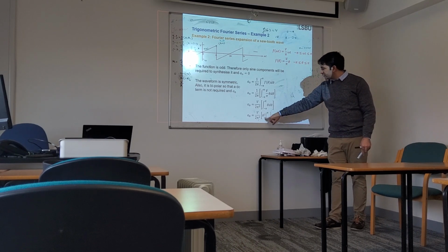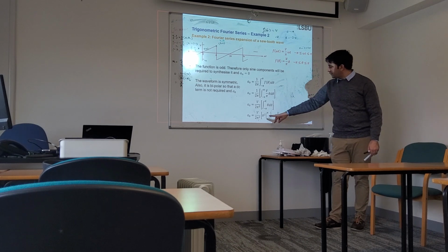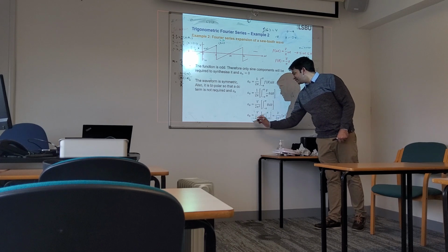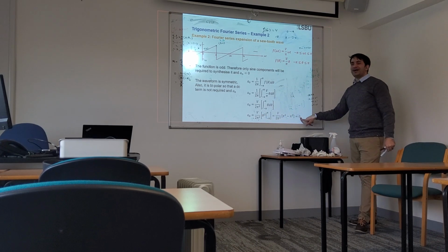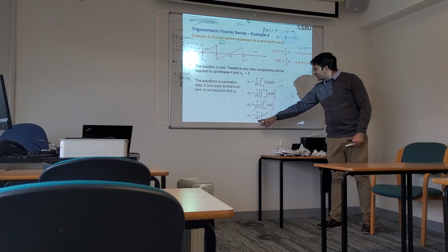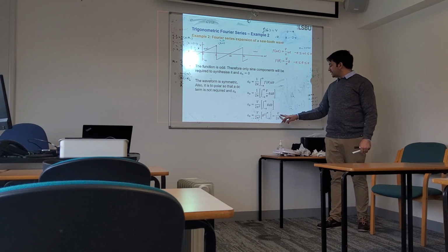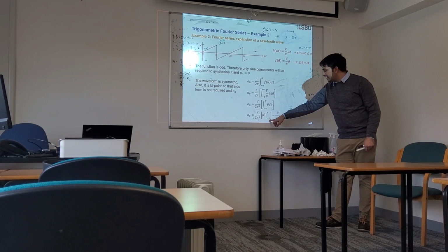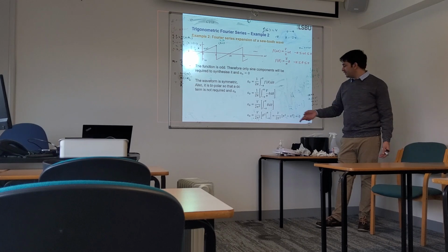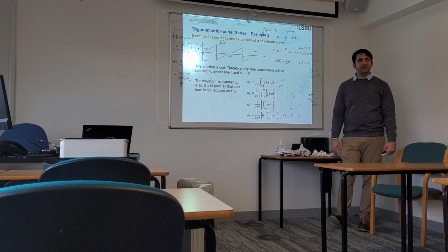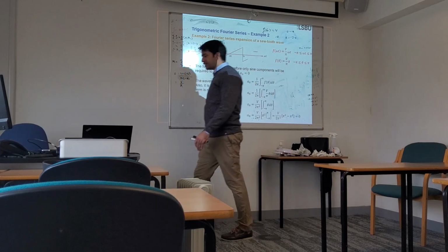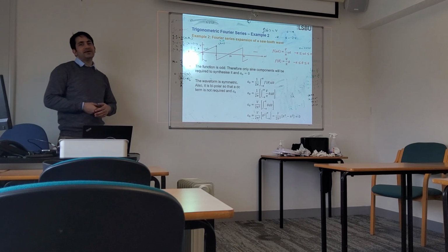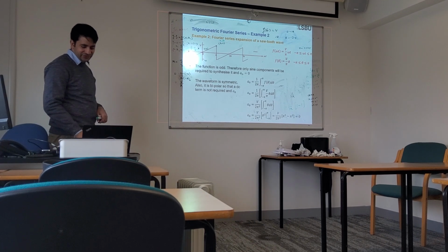So it would be theta squared divided by 2. I don't know where I put 2, but yeah, 2 should come outside. So there is another 2 here. Since I knew the answer is 0, okay. So finally you have theta squared. You put upper limit minus lower limit. So pi squared, then in the lower limit is minus pi, so the square will make it positive. So this will come out as 0. So it means that for an odd signal, the value of a naught is 0, and we also know that the value of a n would also be 0. We can calculate it, and you will see that it's 0.